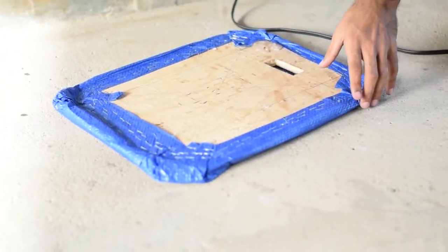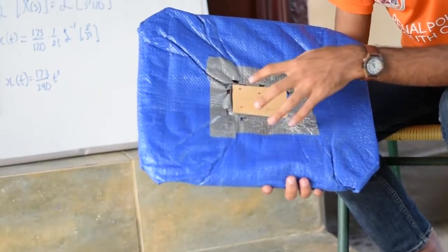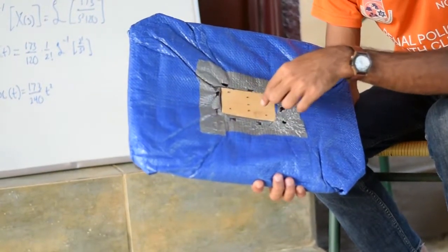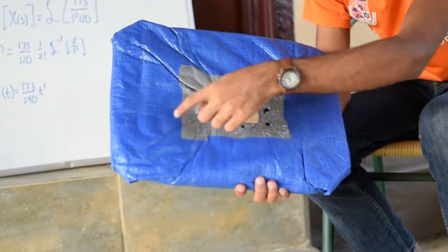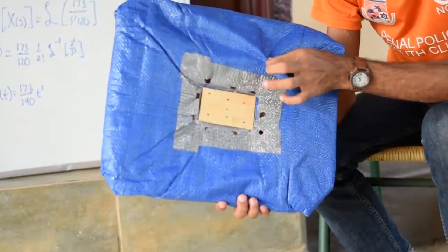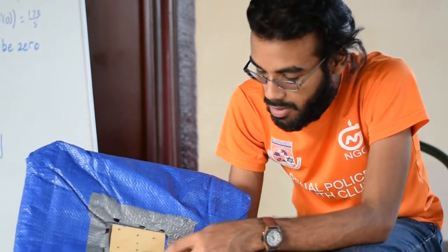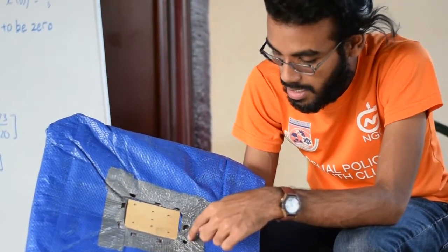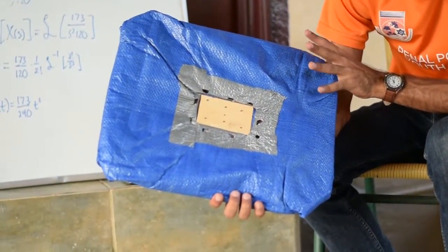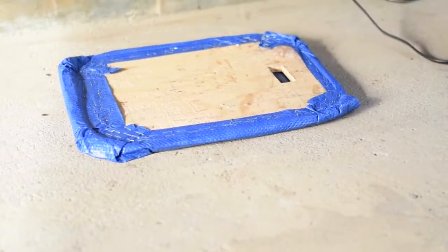This time, in order to solve the problem explained before by the skirt, we actually secured the center of our tarp, or of our skirt, to the plyboard, such that there is no air that needs to be going through this main section to provide lift. Because of this, it creates a smaller area itself that needs to be inflated in the first place, and this will make it easier on the blower we have. As well as we readjusted the position of the holes in it to channel airflow so that we could keep pressure uniform throughout this new skirt design. And hopefully it will work, and as we tested, as we shall see, it did.